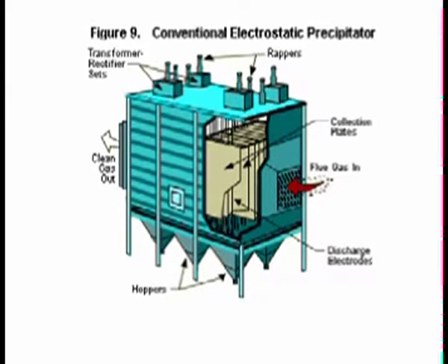Once the dust falls into the hopper, it is either pneumatically collected, or, have you heard about fly ash ponds and things like that? What they do is they bring a water pipe, and the water is mixed with the fly ash, and there is a sluice valve which rotates, and the fly ash keeps on falling down. So you collect it dry or make a wet slurry.